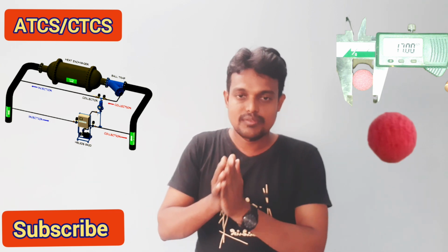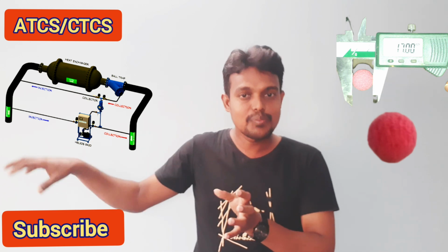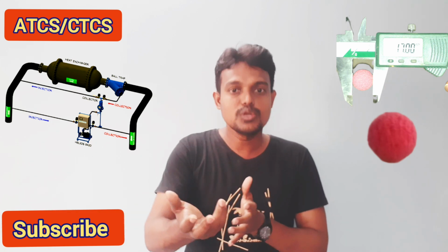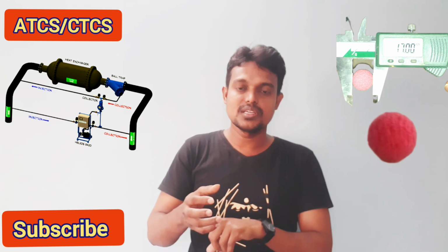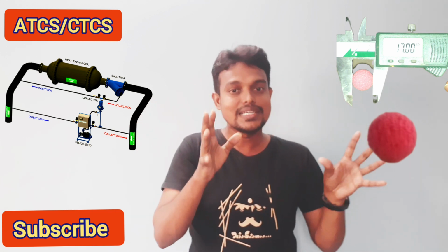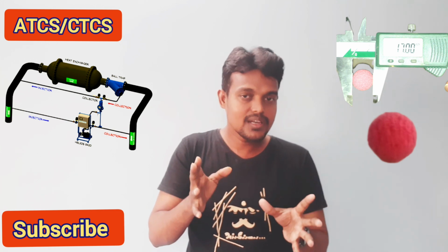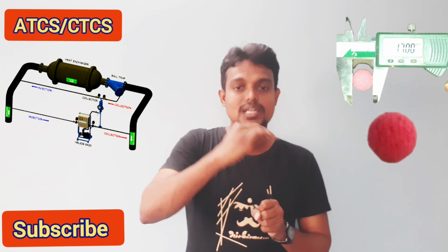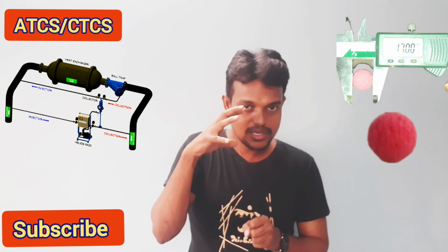The ball collector will be injecting the sponge ball with the help of the external pumping system. Once the ball enters the condenser coil, because of the condenser pump force, the ball will come out from the condenser coil, and it will get trapped in the ball trap. In the trap we have the strainer. The strainer does not allow the ball out of the ball trap. All the balls will get accumulated in the same ball trap.